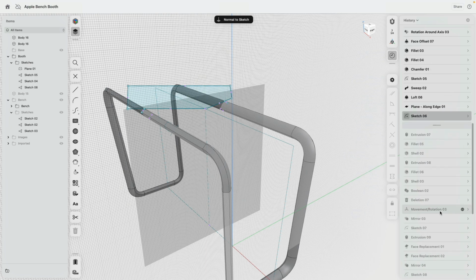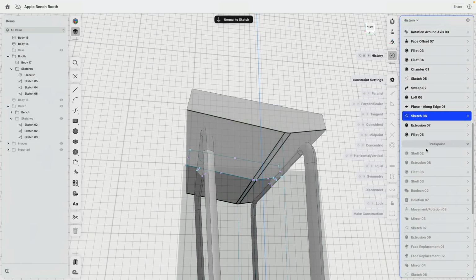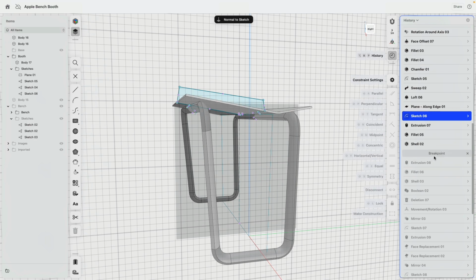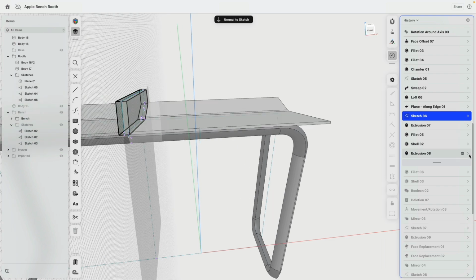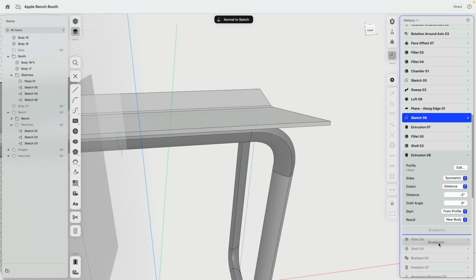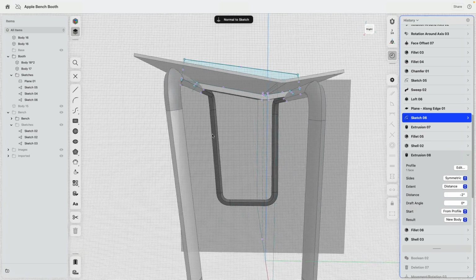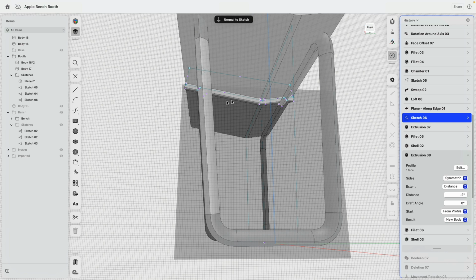That sketch will be very useful because then we can do an extrusion and then I fillet the lower sharp corner and then I do a shell to develop that sheet that sits on top. Then I hide this body, create another piece from the same sketch, but much smaller. And then I do the fillet again. And then I do a shell, but this time the shell goes to the opposite side. So not here, but down there. You see how this is then expanding.